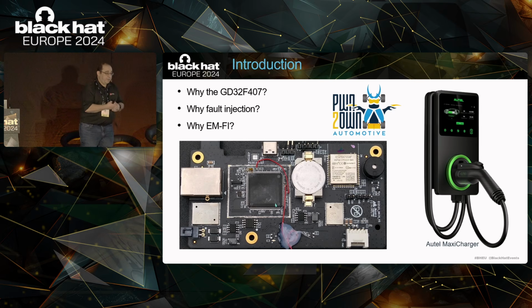Specifically, why EM fault injection? We did not readily have access to any of the internal voltage regulation inside the part. Nothing was exposed, so we felt EM fault injection was the most likely to succeed for this part.